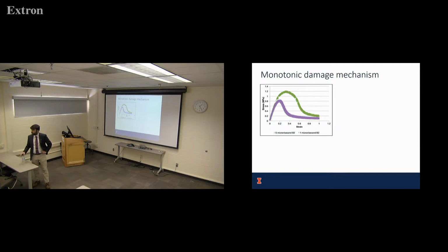One question. For the nanomaterial study, what was prohibiting the dispersion? Because you said for all different testing scenarios, they all clumped. Yeah, I think it's something inherent in the nanomaterials themselves that just dispersing them in any kind of fluid is really difficult. Usually people like to use some kind of carrier to do that dispersion, water or flux. But if you use any kind of flux, like we tried this aromatic flux, it affects the binder properties because you're adding something like a viscous fluid to the binder. Water, the idea is that it'll evaporate, but even water we couldn't get to work well as a carrier. So I think it's inherent in the nanomaterials and they usually need some aid to disperse, but in my opinion, I haven't seen any papers where they found a good one yet for asphalt.